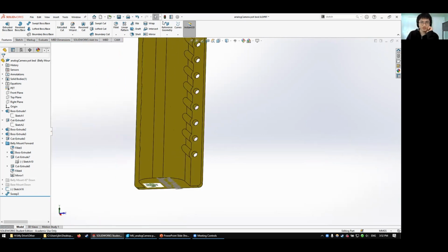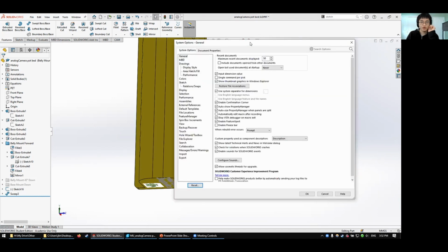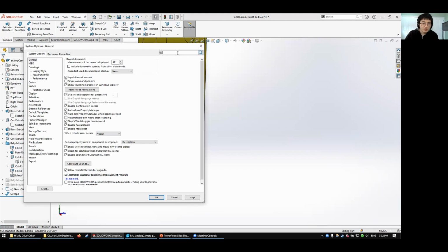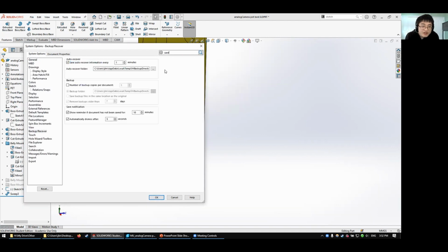Let me see. I think also an important setting to do in SolidWorks is, I think there's an autosave, or at least it tells you where your backup saves are. Backup and recover features. So I set this to 1 minute because I am paranoid. I'm working on a laptop and this thing breaks every so often. So I recommend setting your autosaves very frequently and showing the warnings for saving if you haven't saved for more than a certain time. I recommend those settings.